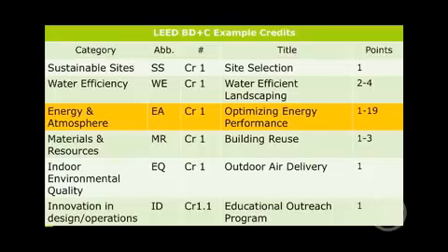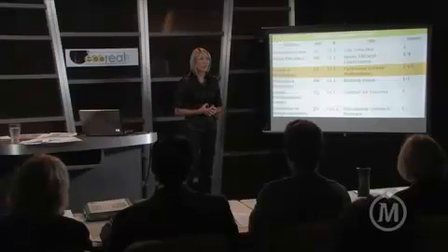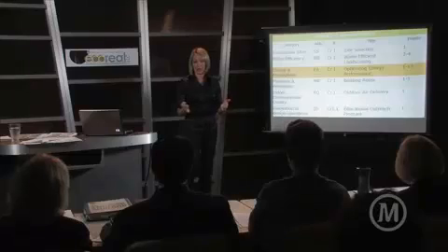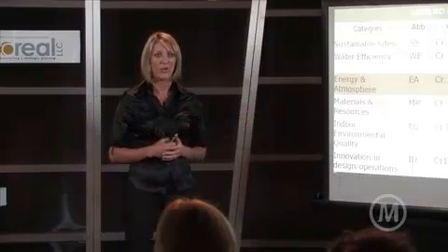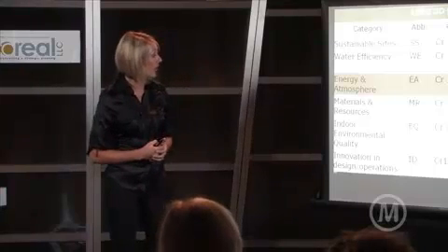Water Efficiency, the first, that's the category. WE, credit 1, Water Efficient Landscaping. This got more heavily weighted. You can earn up to 4 points for water efficient landscaping. A lot of that just has to do with native plants, knowing what is best in your region. So once again, just being responsible, being aware of what the best choices are for your particular project. Not a one-stop shop for every project, being aware of what's best for your climate.